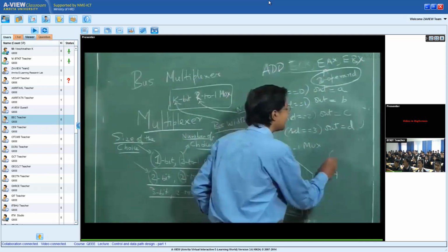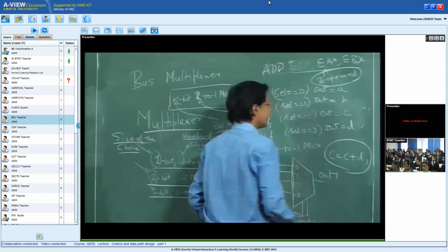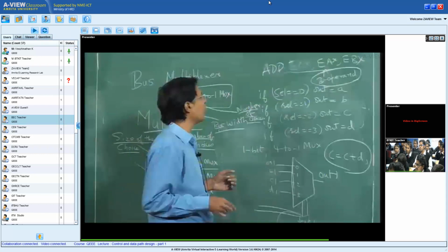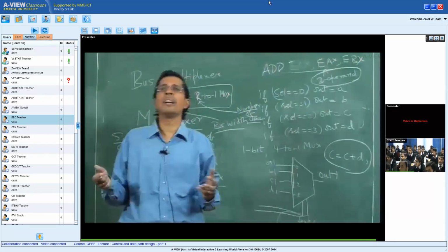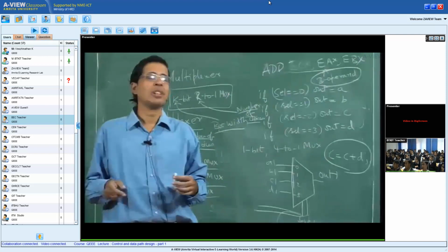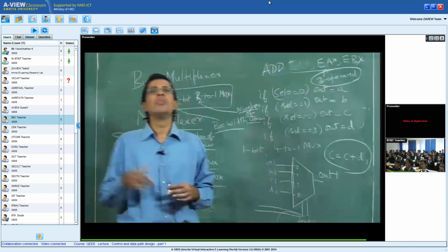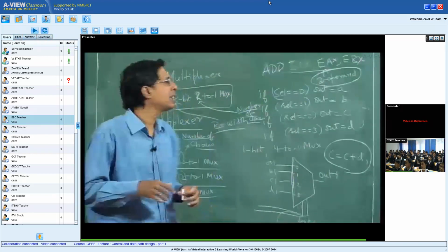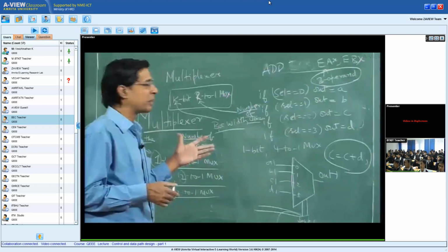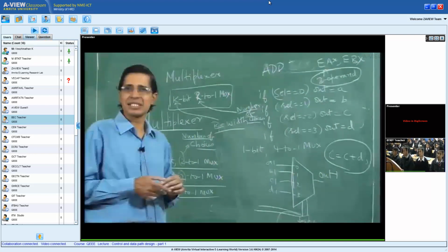It's something like C equal to C plus D in C, right? Something like that is what is happening here, and the reason why we do it is because 3 operand instructions become more complex for you to decode. A 2 operand instruction is much easier for you to decode. When we look at the microarchitecture, if it is a 3 operand instruction, what it means to do will be much different than what we are going to do for a 2 operand instruction.